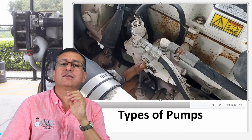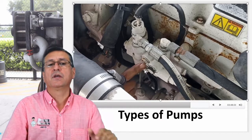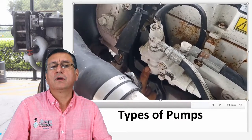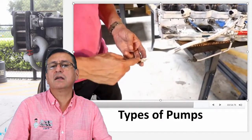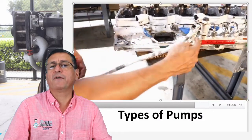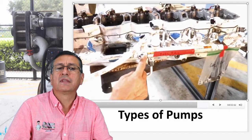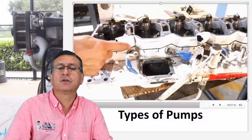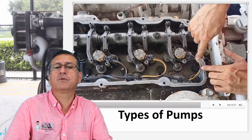And this is the sensor for high pressure, the high pressure sensor. The fuel continues over there, and this is the sensor, and the fuel enters the common rail. Perfect. This is the common rail, and the common rail sends the fuel to each injector, and each injector receives the signal from the computer.